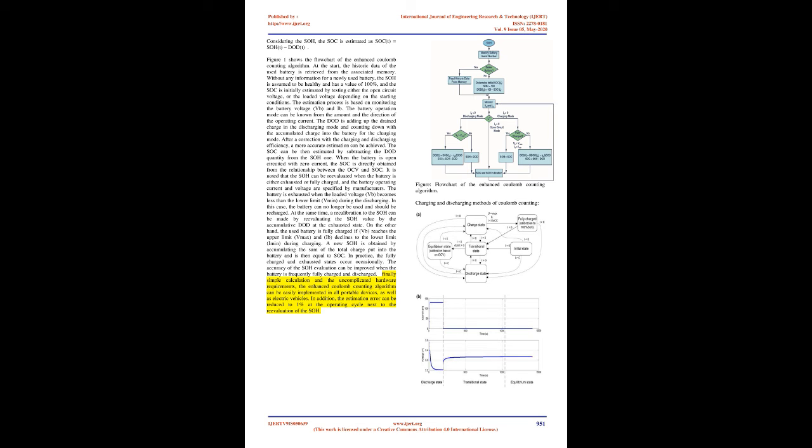Technical principle. The releasable capacity, Q_releasable, of an operating battery is the released capacity when it is completely discharged. Accordingly, the SOC is defined as the percentage of the releasable capacity relative to the battery rated capacity, Q_rated, given by the manufacturer. A fully charged battery has the maximal releasable capacity, Q_max, which can be different from the rated capacity. In general, Q_max is to some extent different from Q_rated for a newly used battery and will decline with the used time. It can be used for evaluating the SOH of a battery.